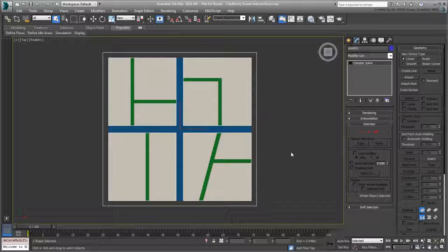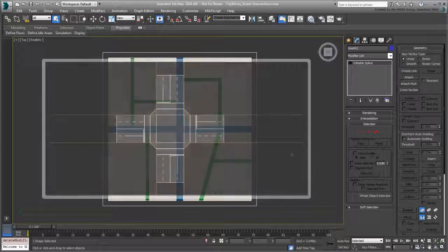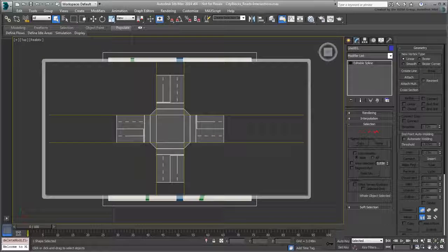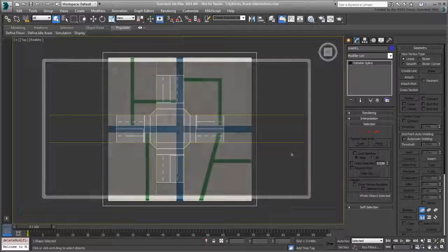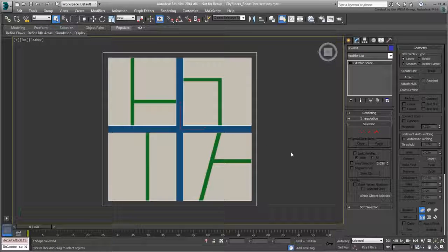As mentioned in the last movie, one of the better workflows, or at least one with the greater flexibility, starts by building road intersections. Road intersections are more than just a square mapped with an asphalt texture. To do it properly, you have to account for various textures, including line markings for pedestrian crossings, lane dividers, and stop lines. You'll start with the center intersection and work your way out.